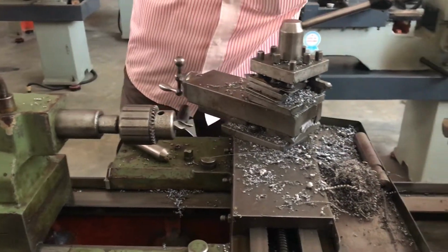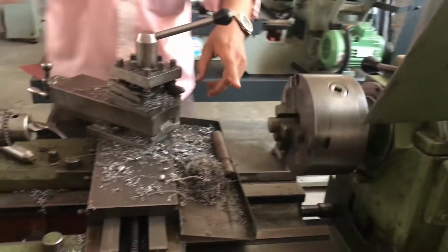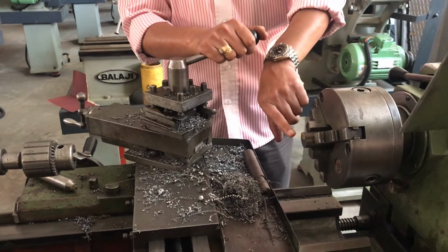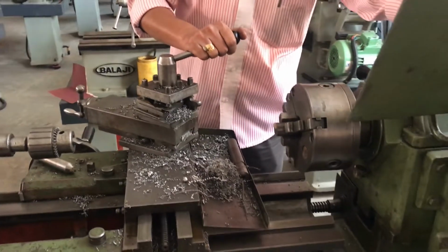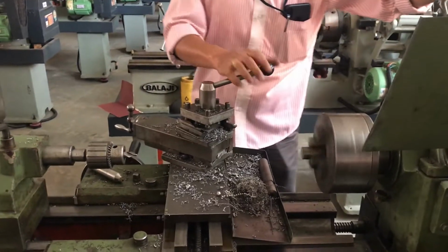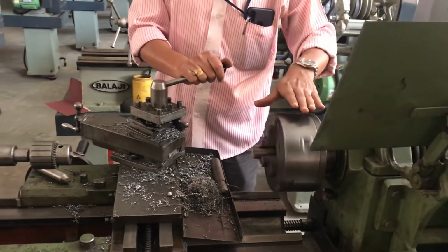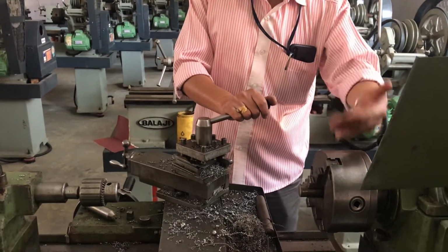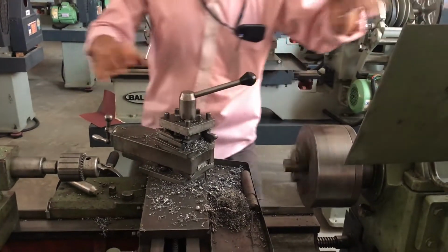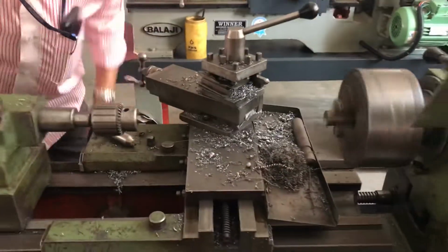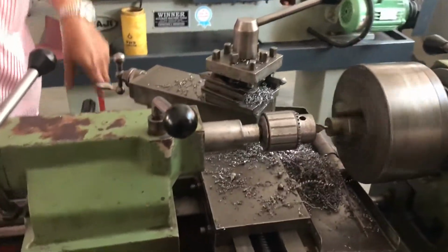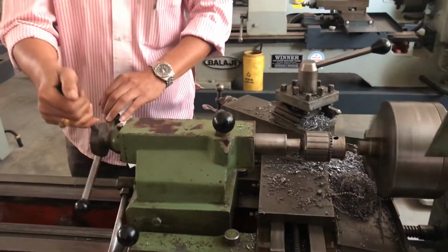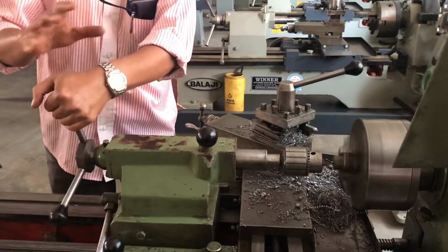After that, while doing this, speed is also very important for lathe operations. Last class I told you. So for doing centering operation, we have to use the second step speed on the machine. And one more important point, this chuck should always run in the anti-clockwise direction. You should not run it clockwise. After that, make it lock and slowly rotate. In the same procedure you can do the drilling operation also.